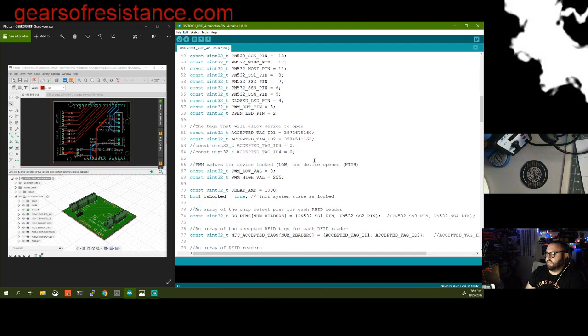All right. Then you have to read the tag. I think I talked about it last time, there is an app on your phone that you can use to scan these RFID readers, at least on an Android phone. I think it's like NFC reader. Usually you'll get a hexadecimal number. Then you convert that to a decimal. There's tools, there's websites to do that too. We need the decimal, not the hexadecimal. And again, if you want 3 or 4 tag readers, you just uncomment and then stick in the tag IDs for those other ones.